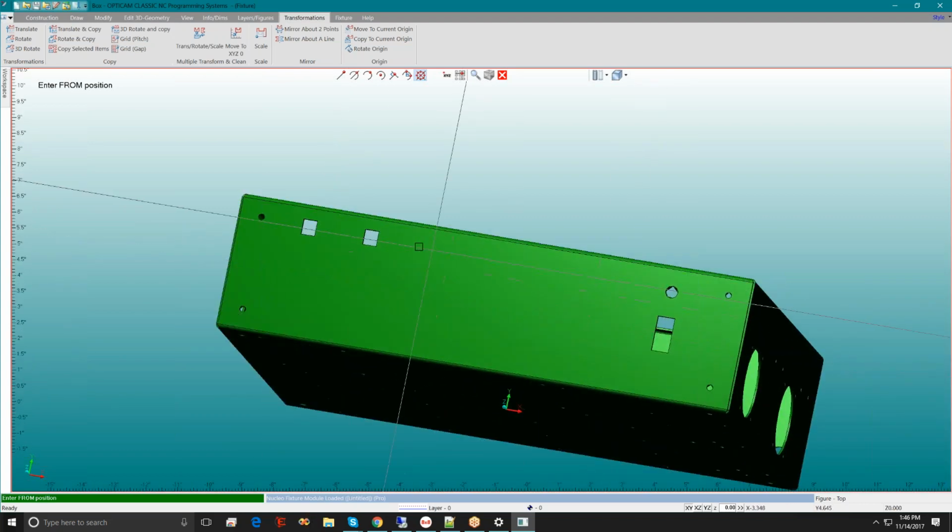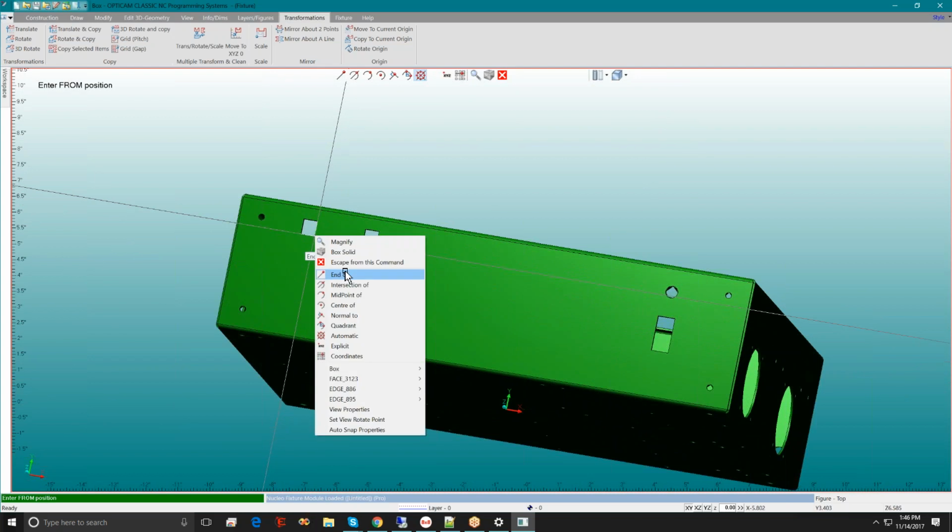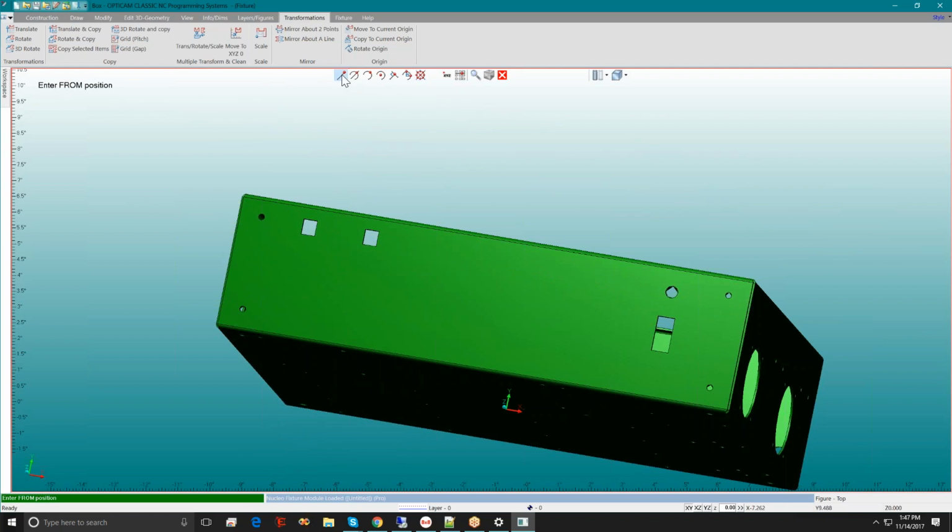You can use automatic, or if you wanted specifically, say, the end of here, you could right click and say end of. And that will, for that one pick only, use end of, okay? But it will still remain in automatic mode for the rest of the picks, all right? You could also press this in, and then it will only pick end of. It won't pick any midpoints. It'll just be end of mode, full stop. It won't change from automatic. It only does end ofs. So these are the modal, the overriding snap modes. And then you can change it to just for one click. You can force it to say end of or center of or whatever. Okay, so they're pretty simple enough.